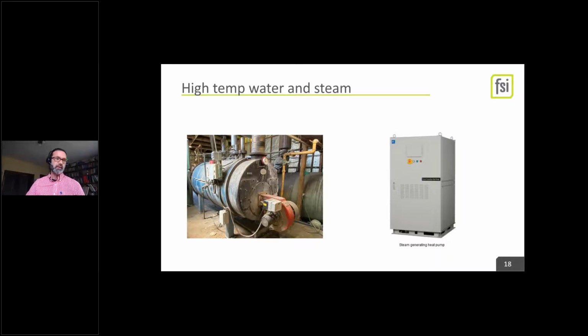All right, we got to talk about high temp water and steam. Similar to that dual duct system, the first time I saw a high temp water system, boiler sitting at 220 degrees, but it was hydronic instead of steam, I had a real head scratcher. So that was an early career learning experience. They're super rare. They were really done in, I think, the late 80s to the early 90s, but they do exist. So if you've got a boiler trying to make 220 degree water, obviously a heat pump won't get there.